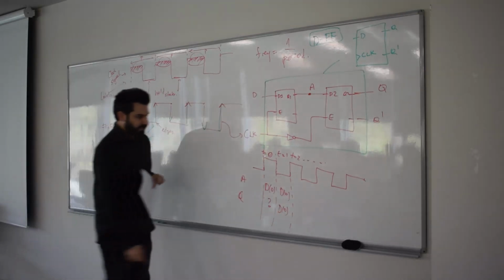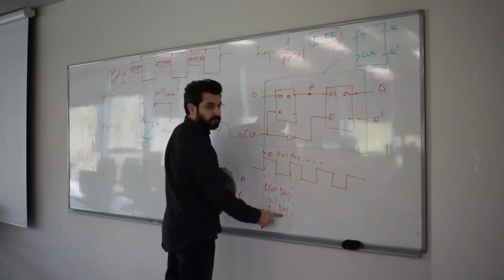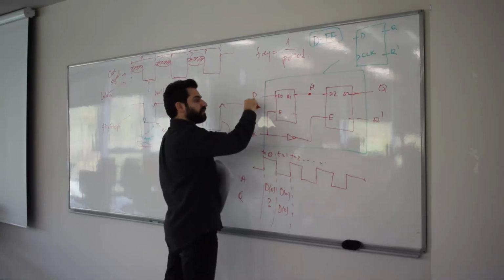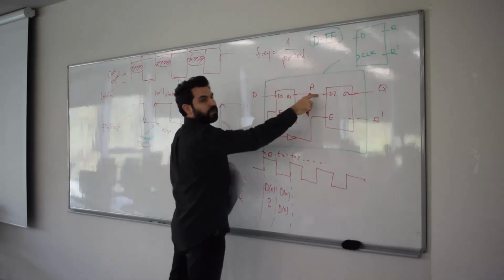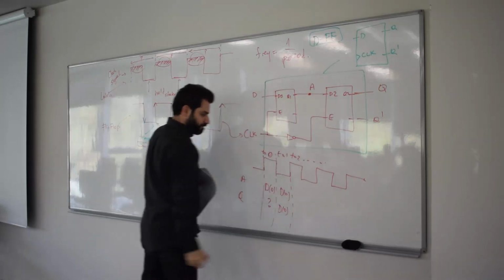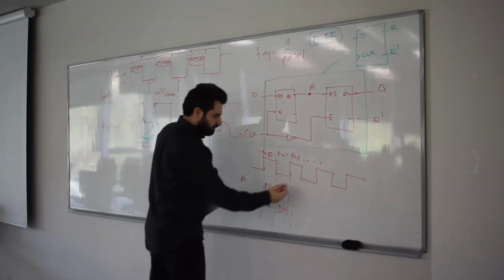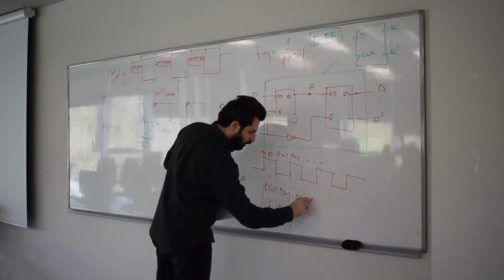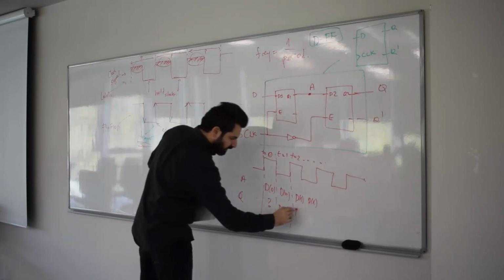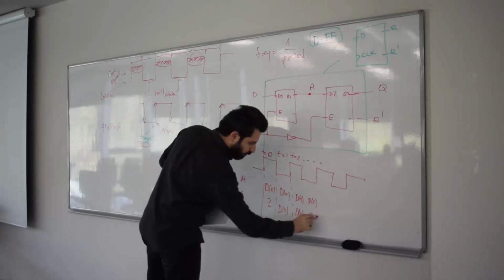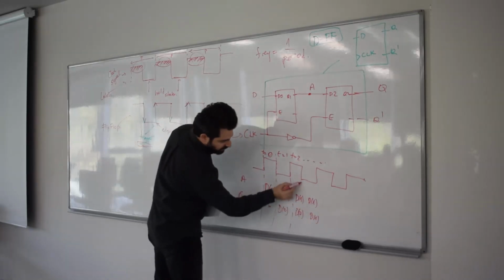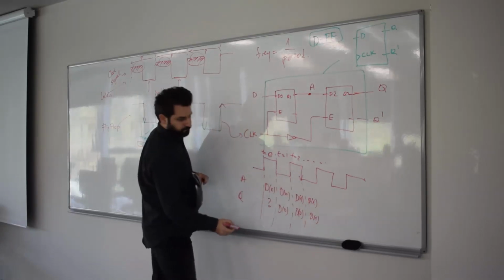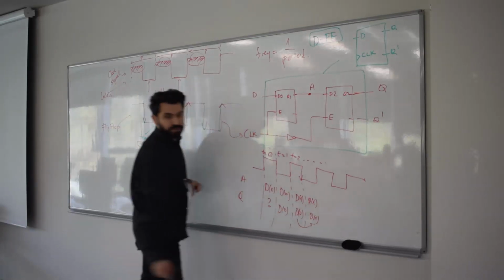Okay? But that D0 is not the noisy version because this is disabled now. The previous D is not copied here. So if you continue the same way, this is going to be D1 and D1, and this is going to keep it D0 and then D1. Okay? Apparently the change happens at the falling edge. This is going to be D0, then this is going to be D1.